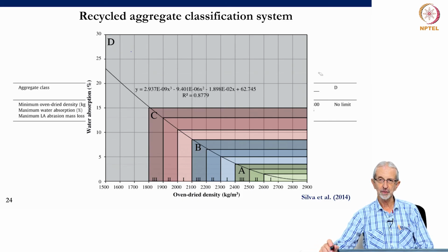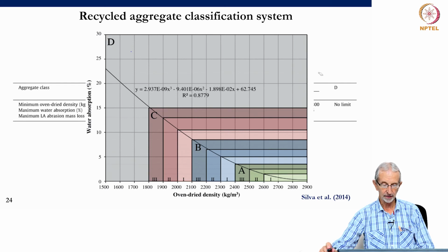And this classification is plotted here in a diagram with colors to differentiate. Again, from the bottom right-hand corner, we get the A category with its 3 subcategories, then the B category likewise, and then the C category, and the D category, which would tend to be only for very low-grade applications, but which in many cases are what we're looking for when we want fairly low-strength block and brick production. It may well be quite acceptable to use those materials.